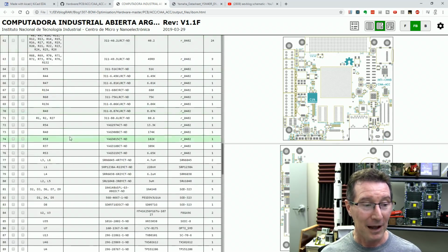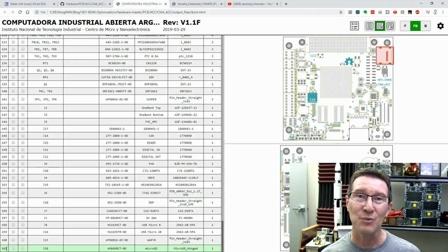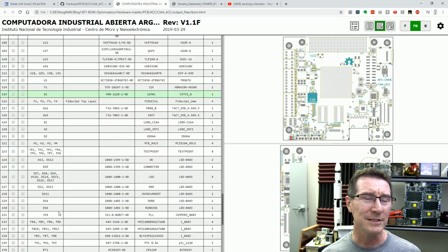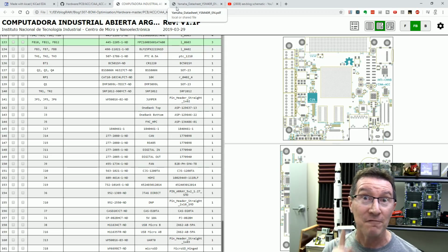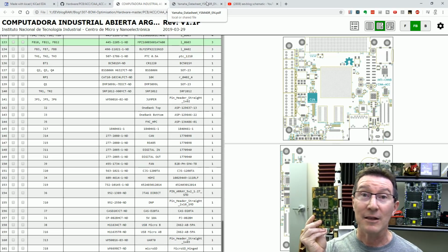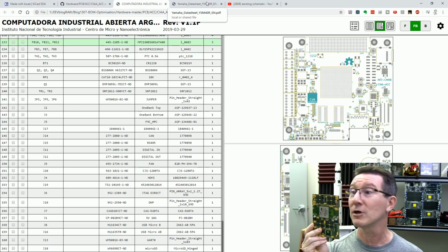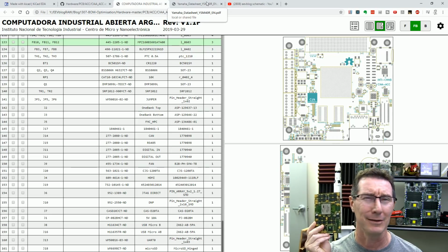And look at all the parts down here. Here they are. There's 161 different components on this thing. Why does that matter? 161. That's interesting. This is where design for manufacture comes into it. Now, of course, assume this is the board, you have to get this board pick and place assembled, because you're not going to hand assemble something like this. I've done it, and don't subject yourself to that.